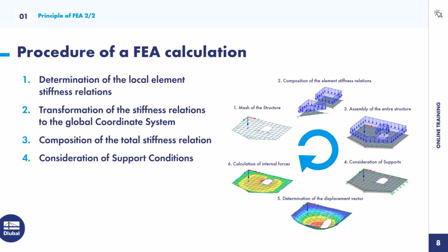It's the stiffness matrix K times the displacement vector U, and it equals the force vector F. So with step 3, we got the stiffness matrix K. With step 4 now, we will get our force vector F. And by considering the support conditions, we can also block or strike out some of the equations, since in the displacement vector, we just set some displacements, for example, to 0.